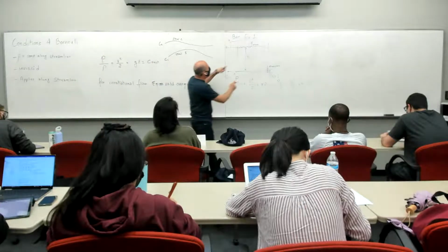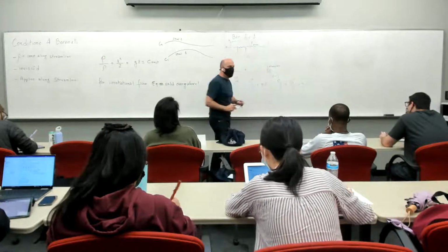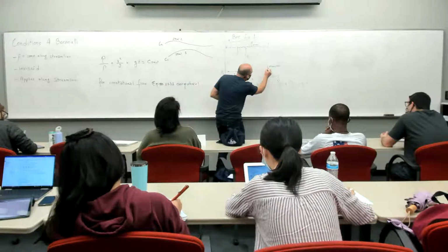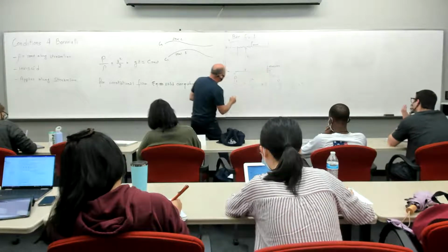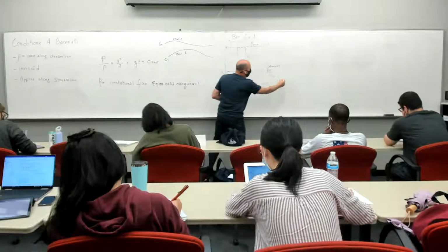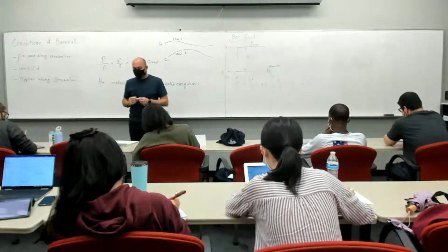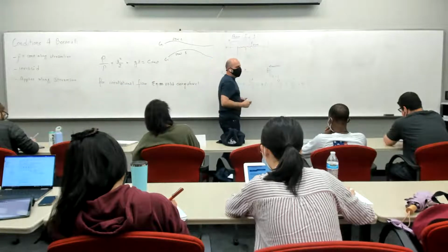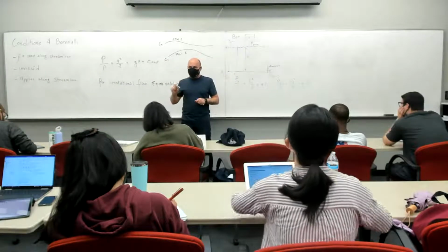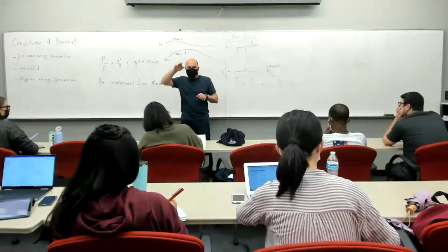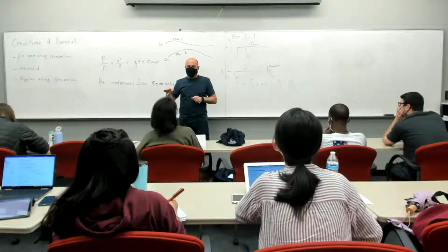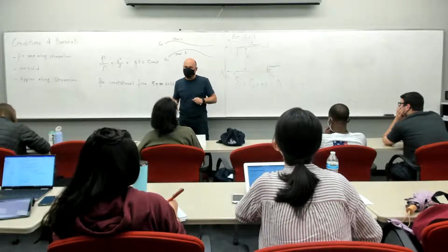Now, both of these are open to the atmosphere, so their pressures are going to be almost constant, almost the same. You can pick a streamline right at the tip over here, it's open to the atmosphere. So you can knock out these two terms. At the surface, the velocity of the surface is so slow that we might as well just neglect it.